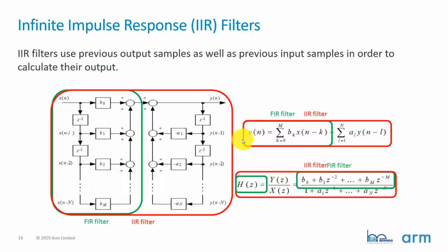The FIR filter version of it is a smaller portion. And you can see here in the actual representative diagram as well, we've got the FIR filter, and then we have the feedback here from the full filter when we're doing IIR. So kind of interesting. Like I said, I don't want to go into the math. I'd rather start to discuss what's the difference between FIR filters versus IIR filters and how that looks when we actually execute them on an Arm Cortex-M processor.